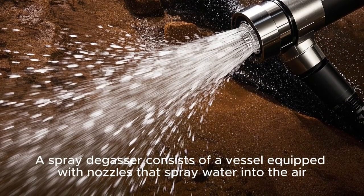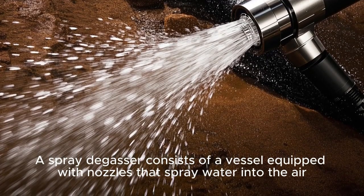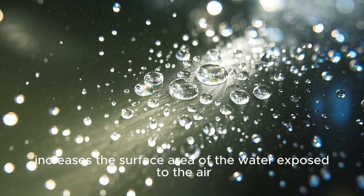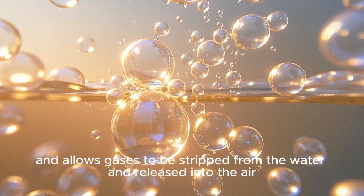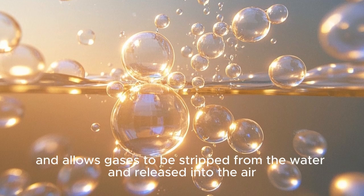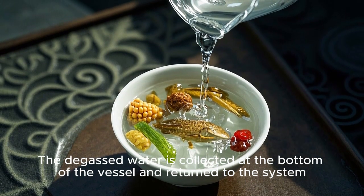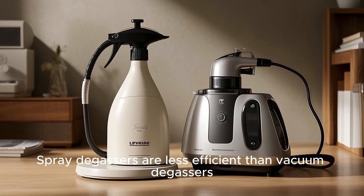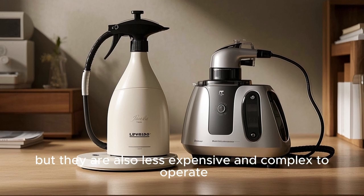A spray degasser consists of a vessel equipped with nozzles that spray water into the air. The water is sprayed in the form of fine droplets, which increases the surface area of the water exposed to the air and allows gases to be stripped from the water and released into the air. The degassed water is collected at the bottom of the vessel and returned to the system. Spray degassers are less efficient than vacuum degassers, but they are also less expensive and complex to operate.